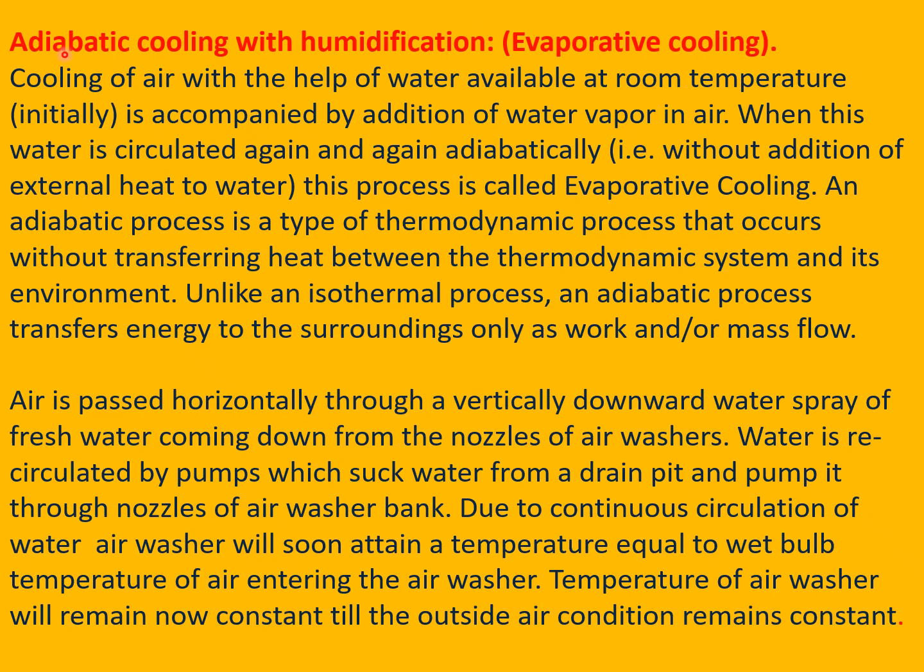Friends, the evaporative type cooling applies adiabatic cooling with humidification, otherwise known as evaporative cooling. Cooling of the air with the help of water available at room temperature is accomplished by addition of water vapor in the air. When this water is circulated again and again adiabatically, that is without addition of external heat to water, this process is called evaporative cooling.